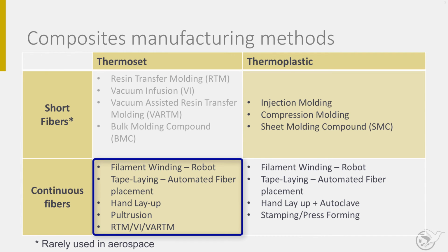First, in all, hand layup of dry fibers or of prepregs. Prepregs are fibrous materials already impregnated with the right amount of polymer. When dry fibers are laid up, a subsequent process can be the vacuum infusion process. By applying a vacuum, the resin is forced through the fibrous material. Resin transfer molding is another infusion process, using matching dies, and is able to apply pressure to force the polymer into the die cavity, which is filled with fibers.